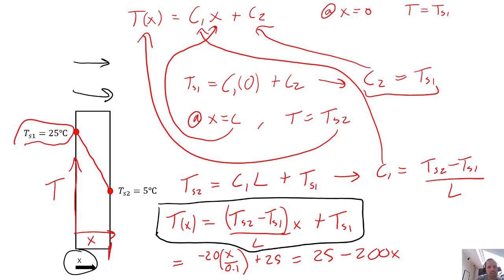Could that ever be reversed? Certainly, if our T2 got much hotter and it became summertime instead of wintertime, then our flow of heat, we'd expect it to go back the other way. We would see that our temperature driving force switches directions, and mathematically we should see that this reverses. So that could be represented by a simple change in our outside surface temperature.